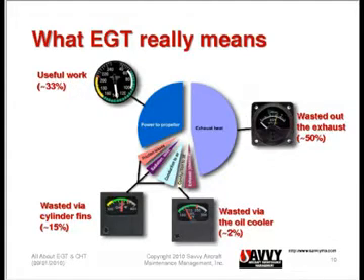The engine extracts as much energy as it can from the fuel, which is typically only about 1/3, and most of the rest of that energy winds up simply going out the exhaust pipe, roughly 50%. If we have a turbocharged engine, we recapture a little bit of that energy that would otherwise be wasted, because we make it drive a turbine and get something useful out of it. But basically, half the energy in the fuel simply goes out the exhaust pipe, which is a little depressing in an age of $5 and $6 avgas, but that's the way it is.